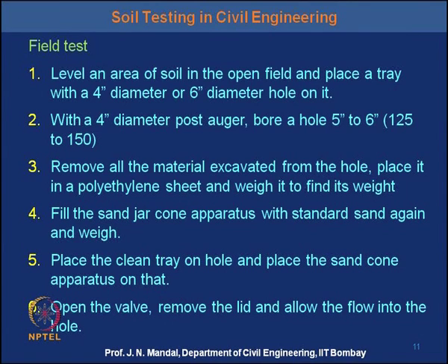With a 4-inch diameter post auger, bore a hole 5 inch to 6 inch deep, that is 125 to 150 millimeter, and then remove all the material excavated from the hole, place it in a polyethylene sheet and weigh it to find its weight. Now, fill the sand jar cone apparatus with the standard sand again and take the weight.